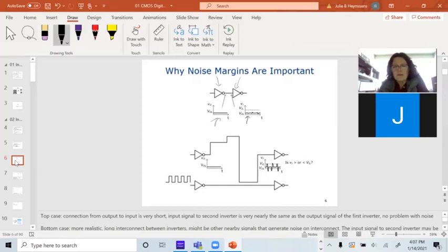This is what I drive out of here. By the time I get to the other side of the wire, I'm starting to see a bunch of little bumps on my signal. That's normal. We accept that generally with digital signals. So what I do, my output voltage is coming out at some typical voltage V out low.